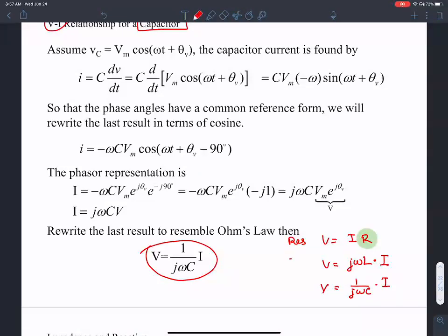When you convert an inductor into the frequency domain, there is a component we call ZL, and then this equation is going to appear like V equals ZL times I. So in some sense, it behaves like a resistance, where V is IR, and Z is called the impedance in an inductor.